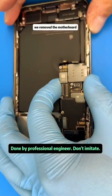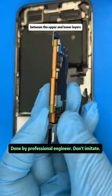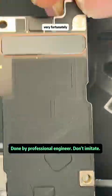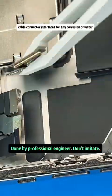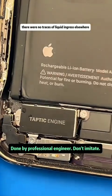We removed the motherboard. We needed to observe the seam between the upper and lower layers, as well as all connectors and sockets for external accessories to see if there was water ingress or corrosion. Very fortunately, the motherboard had no corrosion or liquid ingress. Next, we checked all cable connector interfaces for any corrosion or water ingress traces. Very fortunately, there were no traces of liquid ingress elsewhere.